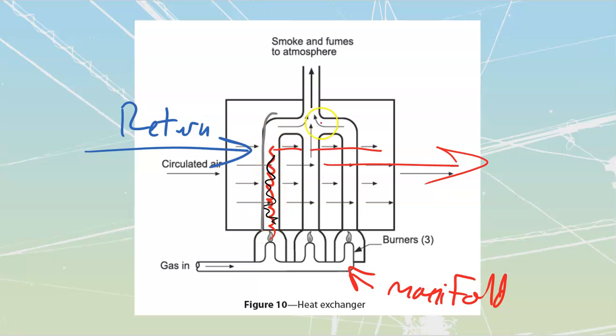What we're seeing inside of our heat exchanger over here as well is that the heat exchanger air is going to get cooler. As it works through that system, it goes from being really, really intensely hot down here to becoming cooler and cooler. We bleed the heat off into that system, and by the time we're exiting the stack over here, all that we're exiting with are my products of combustion and relatively cooled air. They are going to be fairly efficient. They're not great, but we are going to be able to strip most of the heat out of our air and into my return air.